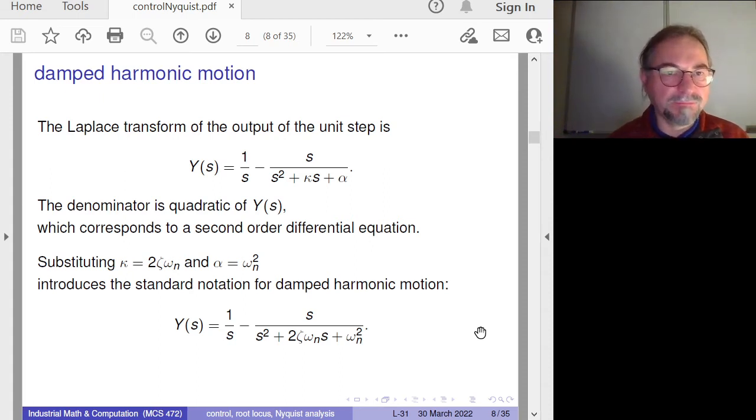And most importantly, for this example, why do we do this? Well, we want to design parameters. With the damped harmonic motion, going in the notation for the zeta and the omega, we could actually determine the shape of the response. Think about the car suspension mechanism. We wanted a design that didn't overshoot, and we could also design how fast the car suspension mechanism returned to its original state. So that is a brief recall of damped harmonic motion.